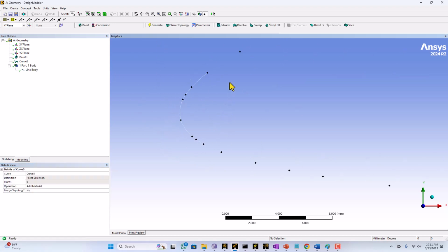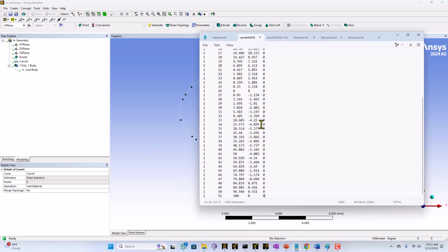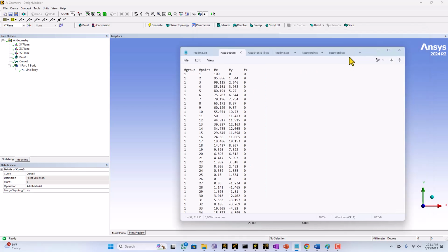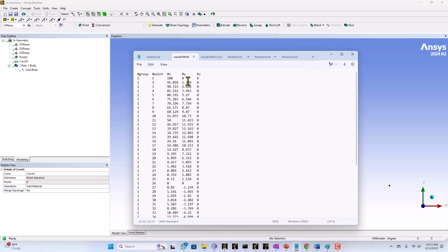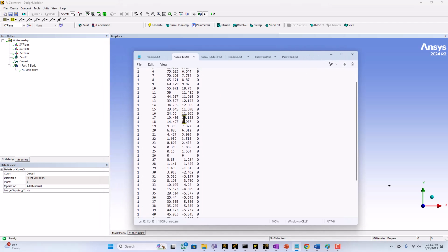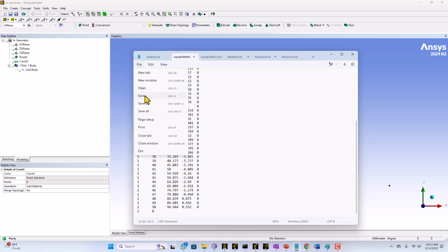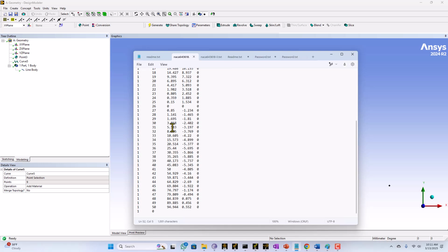So now the thing is that if you are having that file, I had the file which was a square trailing edge. Okay, and so what is a sharp trailing edge? The last point is always the same point as at the start. What we usually do is put the last point as 0, and we don't put any coordinates at all. This is the file format for the curve. If the trailing edge is sharp, it means that it's joining at the point.